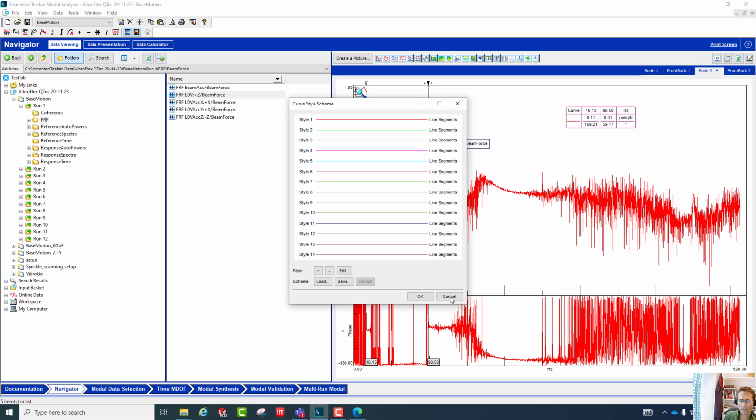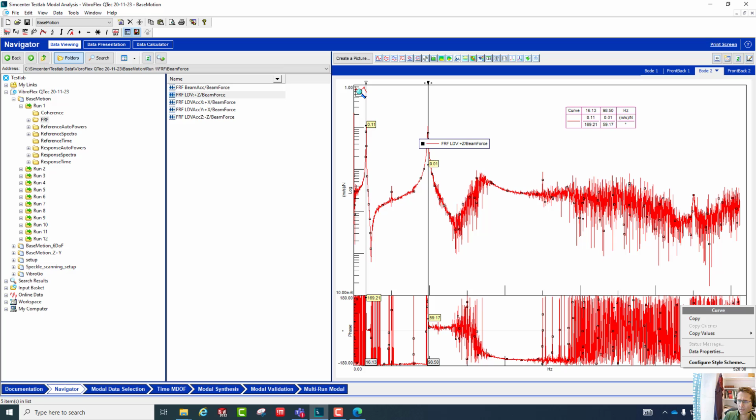I know that I've only got excitation in this case up to 100 Hertz because I specified that in the measurement campaign. I'm trying to double click the axis system here to be able to change the limits. I think that seems to have done something that I shouldn't have done because it's now giving me a hard time. So there's a window open somewhere that is preventing me from going further. I can change the axis system to get a finer, more detailed view on these data.